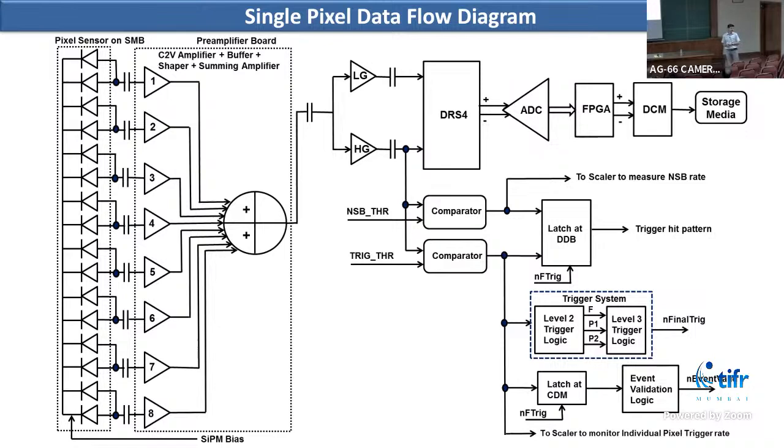What is your criteria to identify a signal as low gain? It is one signal, one pixel output only. Here we keep the gain less than 1 so that it can cover the full dynamic range of up to 1500 photoelectrons. At the same time, we want the small signals to be accurately digitized.